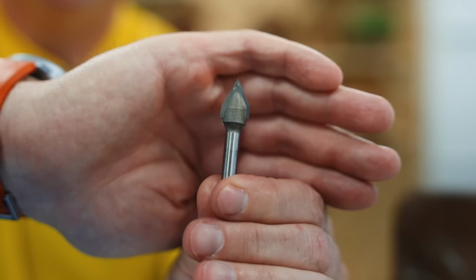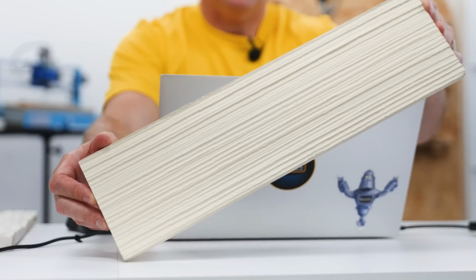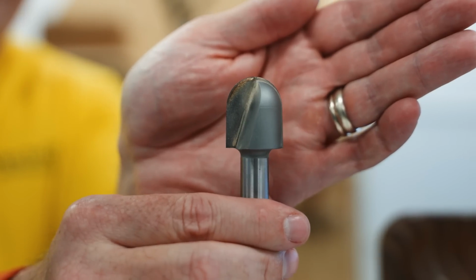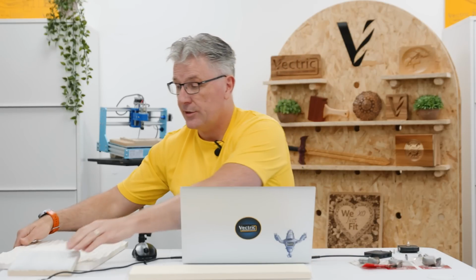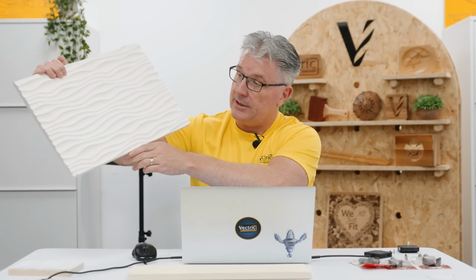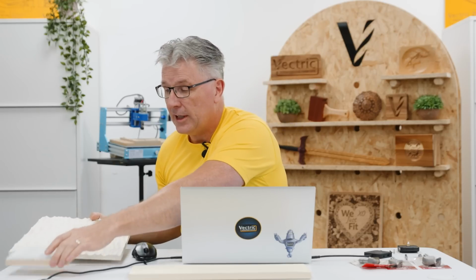The first thing I want to point out is that these textures can be created with all kinds of different actual cutters. We've got a V-bit that will create something like this sort of a wood grain texture. We've got all sorts of different size bullnose cutters, and they'll create all kinds of interesting textures like this larger one that we have here, which is really quite nice in the end. So when you're thinking about using this tool, you might want to think about what cutters you have on hand and what different results you can get by using those cutters.